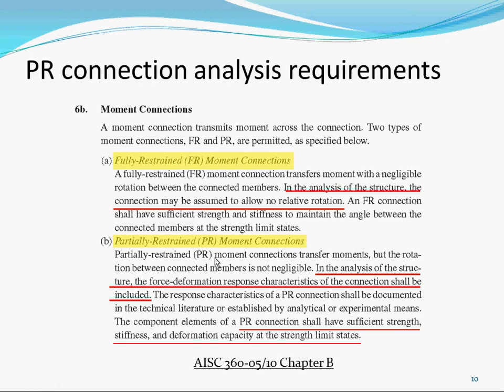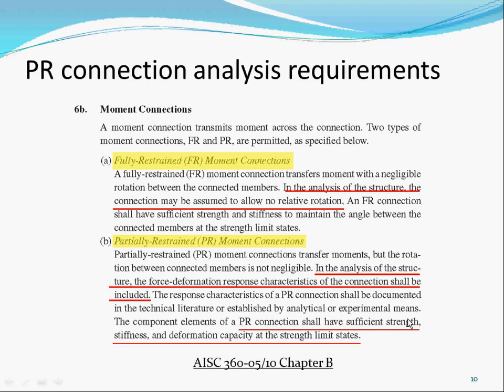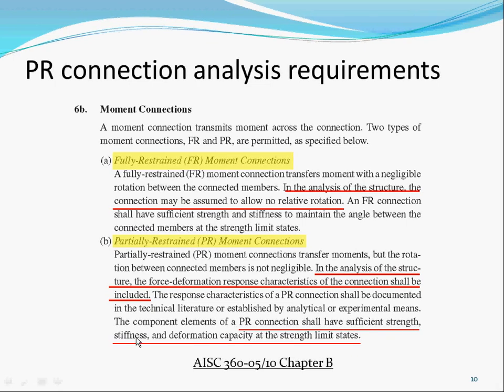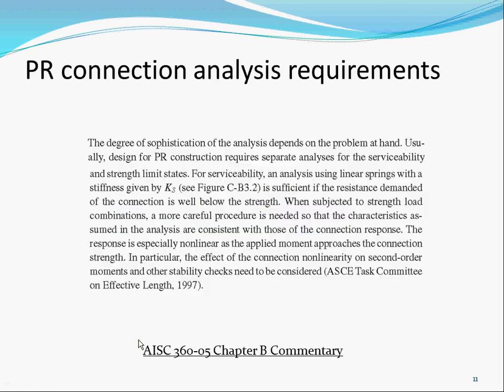Now PR connections must have sufficient strength, stiffness, and deformation capability. Strength and stiffness are the two we're gonna calculate. Deformation capacity, we tested it to see if you're okay or not. So we meet one of them already, the deformation capacity. But during design, we need to make sure it has enough strength, obviously. And the stiffness, it's the drift when you're checking. I'll go into each of those later.